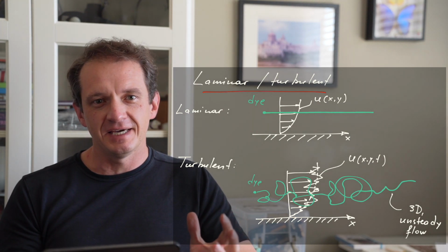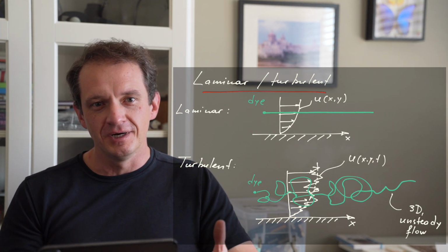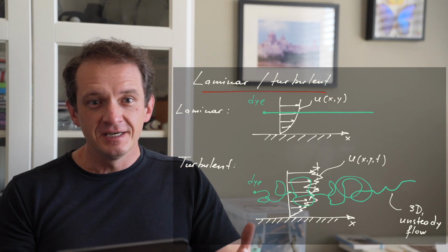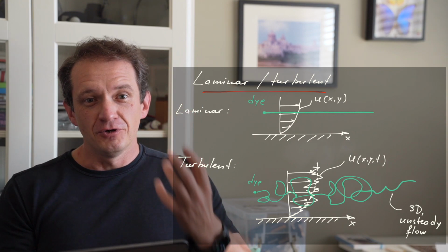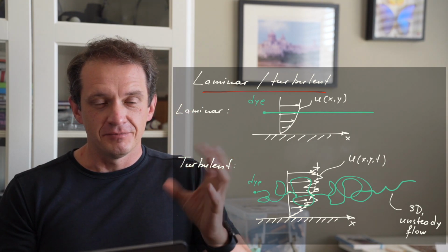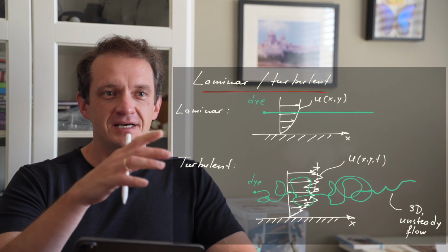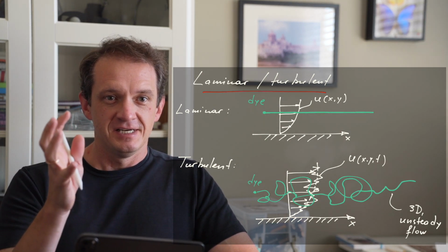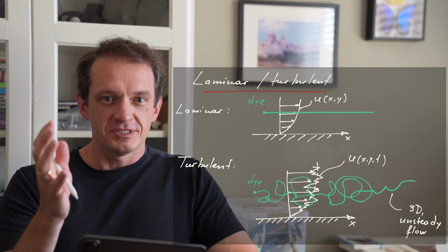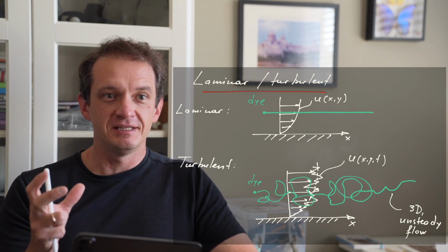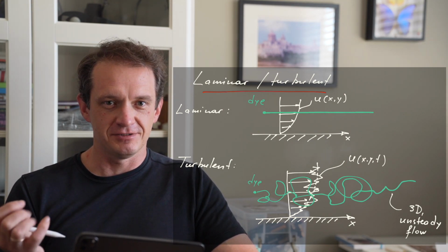One thing we can say is that turbulent flow is necessarily unsteady and 3D. The flow parameters such as velocity components and pressure fluctuate. So the flow has vortices or eddies; it's composed of these vortices. They are oriented in the three dimensions, and there is a large range of scales of those vortices.